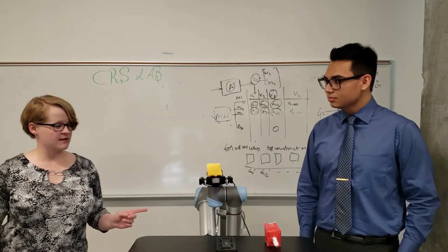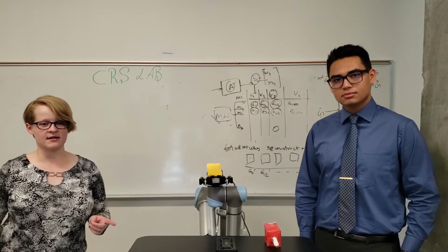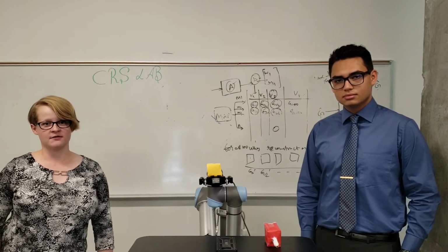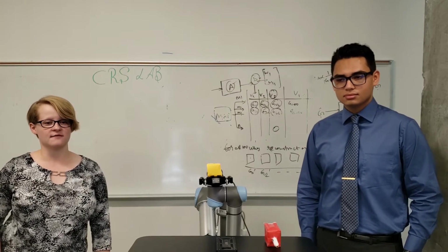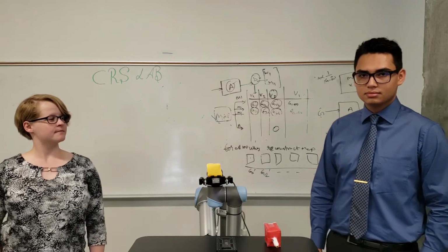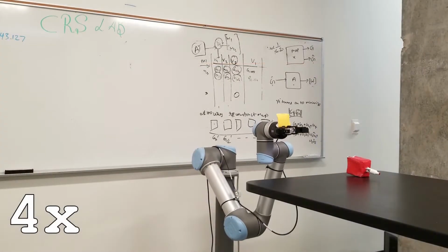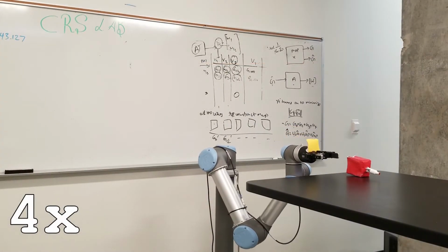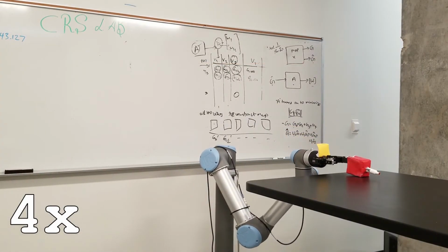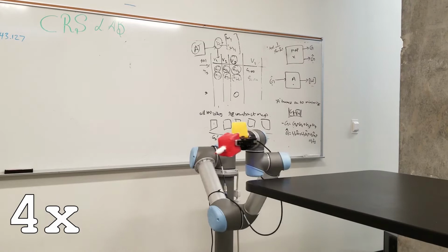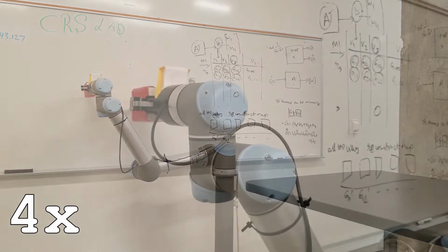Once it has calculated the center, it checks the Kinect image for the corresponding depth values in that area and returns an XYZ coordinate for both objects. As it sends these coordinates back to the Ubuntu machine, adjustments are made for the UR5, and another script slowly moves it toward the block until it's within distance that it can grip the block and run another script that will bring it to the board.